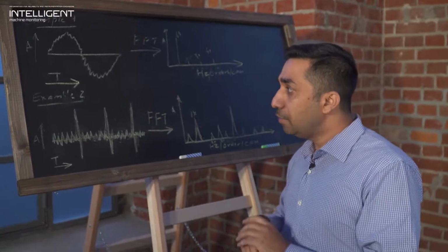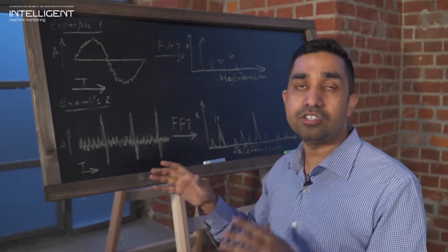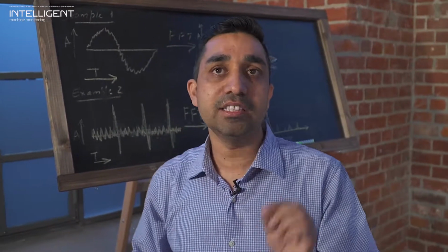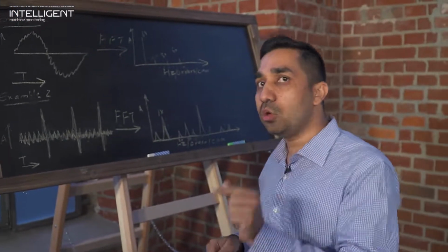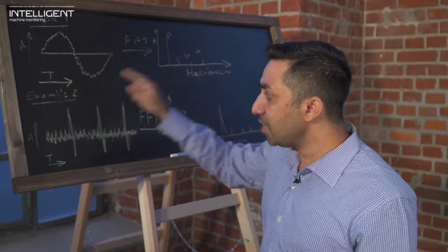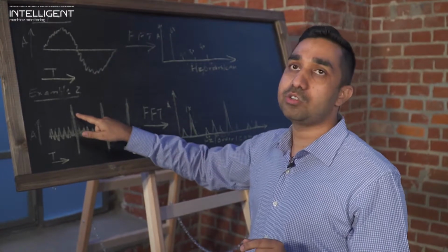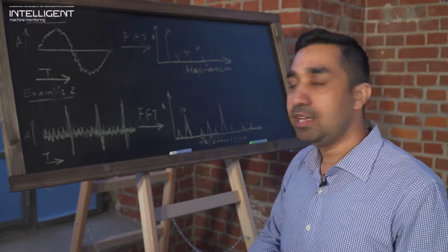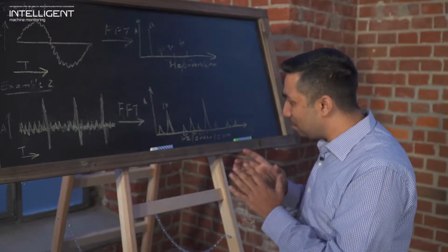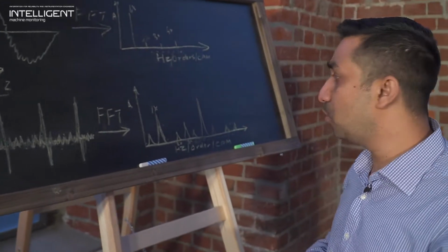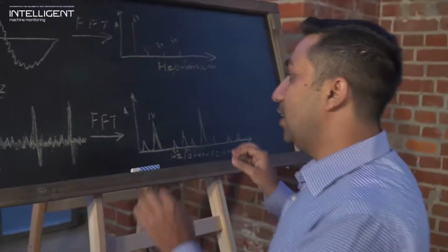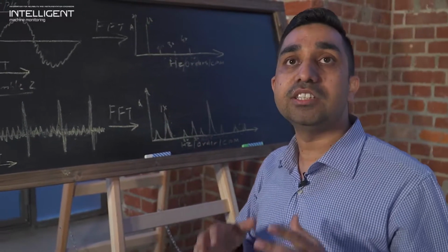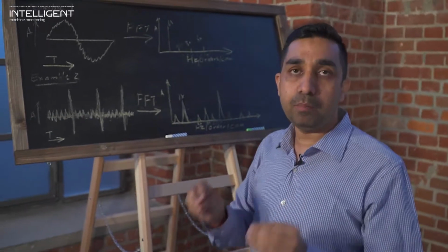Okay, it's fine. But in the second case, there is a fan driven by a motor via a belt drive, and this belt has a localized fault. And whenever this localized fault passes over the pulley, it will create a transient like this, and like this. So it is clearly visible in the time signal. But if you see the spectra, I need to put in too much brain to figure out what's going on with this machine. It's really important to look into the time signal, and in the second example, the time signal gives you a clear picture of what's the problem in the machine.